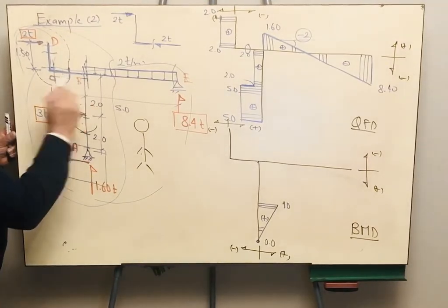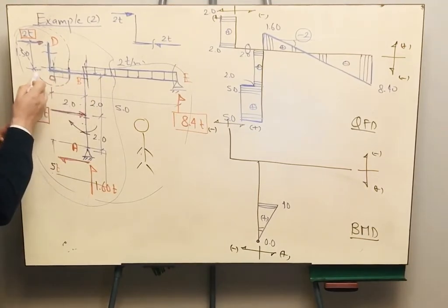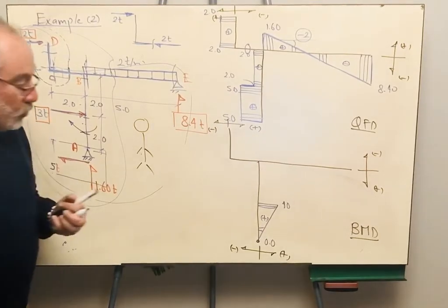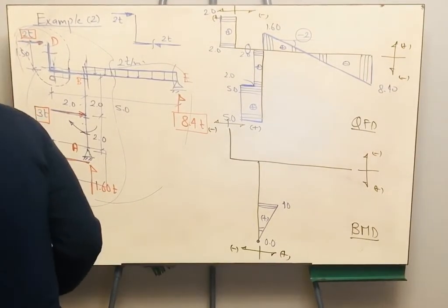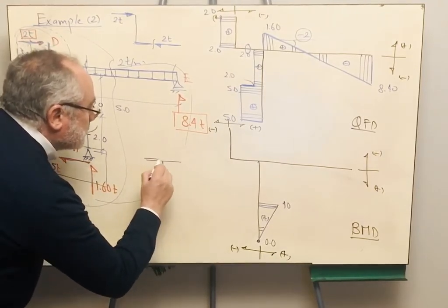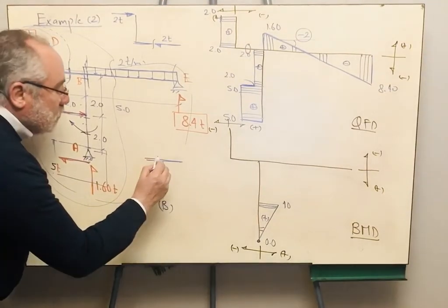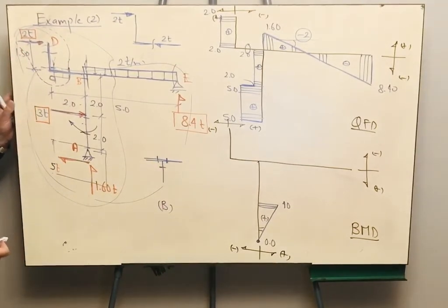What will be the bending moment at point B? Take care. Always I want you to show me the free body diagram of point B and point C, because there you are having so many members connected, you have to make sure that the bending moment is in equilibrium. Let me start with point B here to show you what we should do. For point B, we are having basically 3 points, right? This is point B. We can calculate the bending moment on the right and below, and the bending moment on the other side will be obtained from equilibrium.